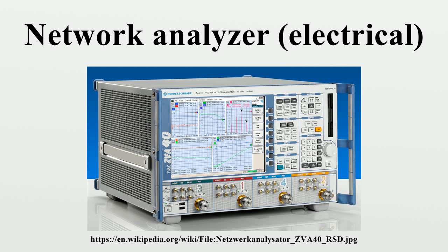The definitions of the standards for a particular calibration kit will often change depending on the frequency range of the network analyzer. If a calibration kit works to 9 GHz, but a particular network analyzer has a maximum frequency of operation of 3 GHz, then the capacitance of the open standard can approximate it more closely up to 3 GHz, using a different set of coefficients than are necessary to work up to 9 GHz.